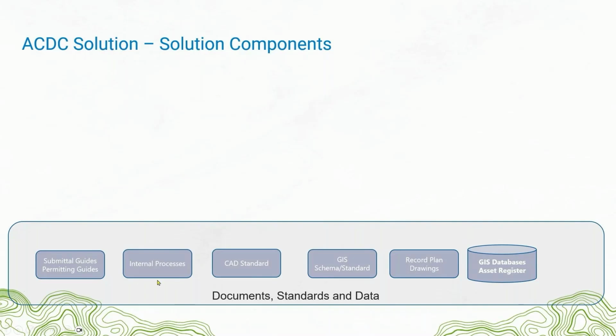We usually start with whatever you have. So I ask folks, do you have a CAD standard? And they may say yes or no. And I'll say, but do you have a GIS standard? And they may say yes or no. At which point I'll typically say, well, you actually do. The actual feature names, asset types, domain values, column names, and everything that you have in your GIS, that is your data standard. And if possible, you should match the incoming data to that. So we work with that.